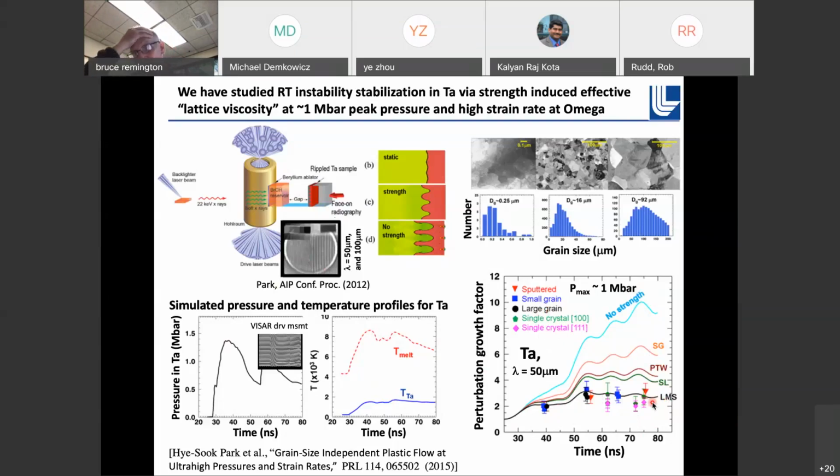So we did not see the Hall-Petch effect. We did not see small grain structures looking to be harder than large grain and so on. They all looked the same. And so we guessed that the dislocation density was so high that all of the plastic deformation was happening within grains, and never really cared about the grain boundaries and the size of the grains because they were large. It was large compared to where the plastic flow was actually happening. That was the assumption.